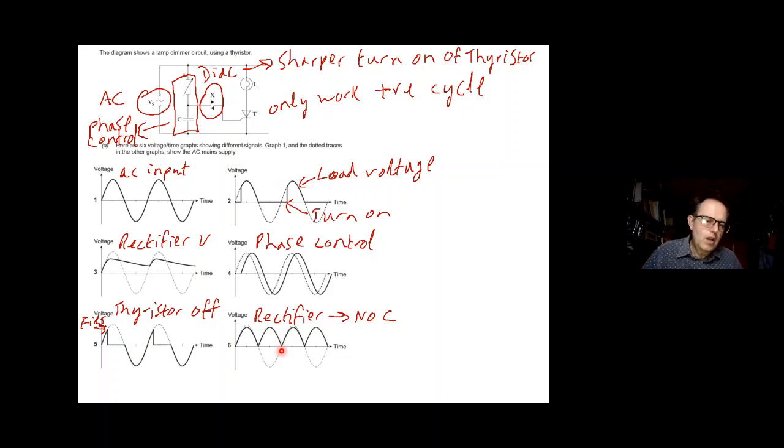So they're testing us here to know, do we recognize the sort of voltage values which go with this circuit? The two which are really important, I would say, number one is recognizing that that shows the voltage of a load. Now that and that are opposite to each other if you look at them. With this one, that's where the thyristor is off, but it fires there. And once it fires, there's no voltage drop across it. The negative cycle has turned it off. And then whenever the thyristor is off is when the load gets the voltage. So that's important in recognizing those little voltage points.